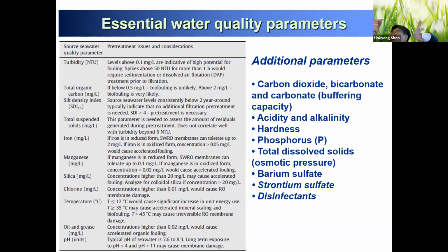And your water molecule at a temperature of 25 degree passes through faster. At a low temperature, you have more viscosity, and then you have a longer traveling time through the membrane. One degree will change 2% of your overall flux capacity. So if you increase 1 degree, you have more water flowing, more water production, and you have to calculate this because the water keeps moving depending on the temperature.